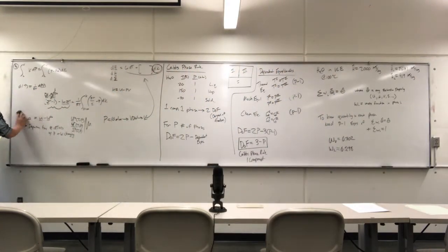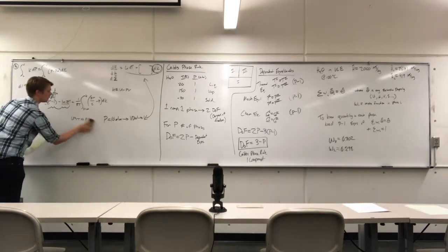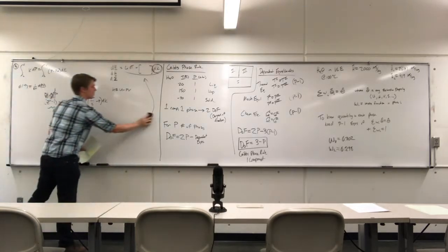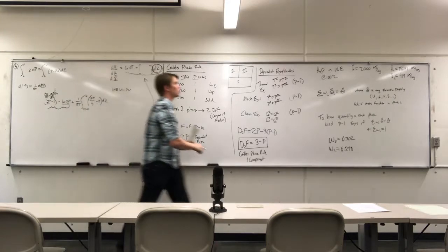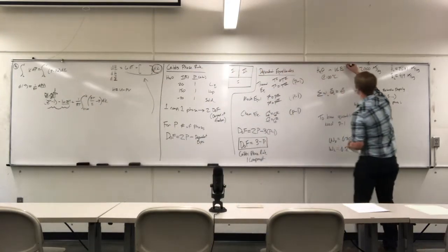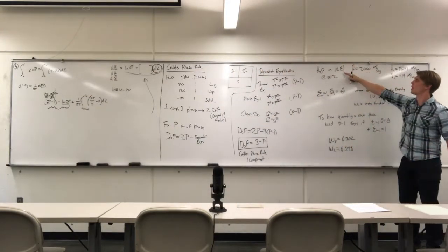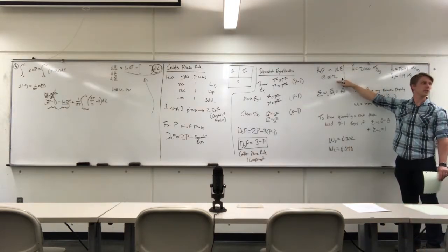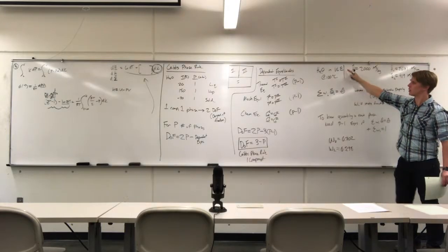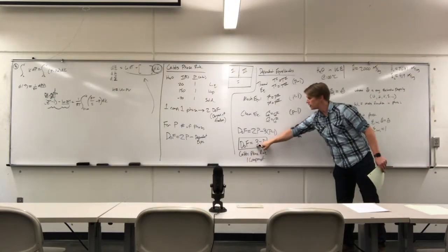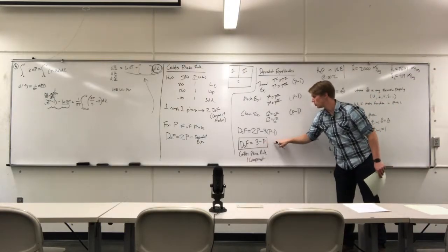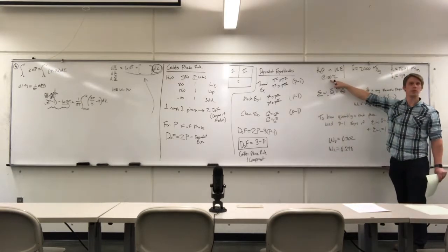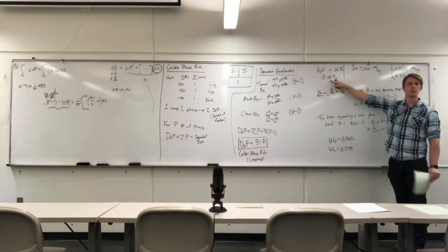I have a question. Yes? Do we not need to know the pressure to get the enthalpy from a table? We would be able to look up what the pressure is based on this information here. So if we know that water is in vapor-liquid equilibrium at 100 degrees C, that fixes our position in space. So when we're in vapor-liquid equilibrium, we have two phases, 3 minus 2 equals 1. The one additional variable we define is the temperature.